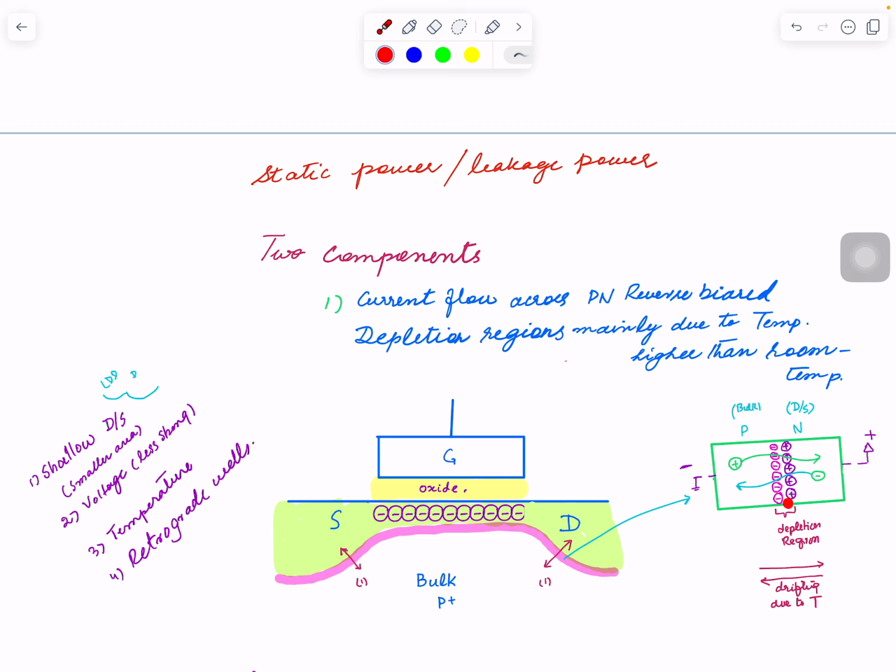Similarly, electrons at the boundary. When you bring them together, first the people at the border do the migration. I gave that analogy of immigration. They leave the country. So as soon as these electrons leave, they leave behind a positive charge. These negative and positive charges get stuck with each other, and they create a wall that stops further flow. That's really the depletion region.